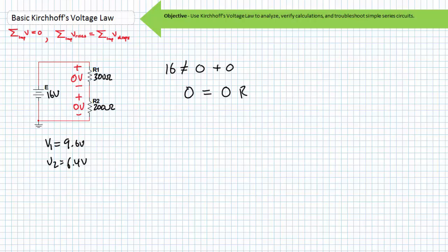However, it would not necessarily be of any use in pinpointing the error. Visual inspection of the circuit might yield a faulty connection or errant wire. However, let's see if we can use our voltmeter and Kirchhoff's voltage law to pinpoint the error via comparison of our expected and observed properties. If there exists a voltage rise, there also exists a voltage drop. Where the drop occurs is across the open.